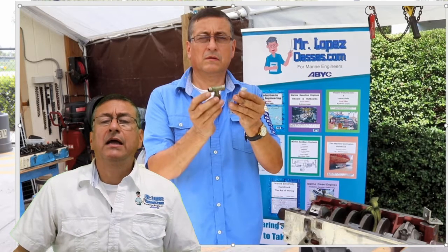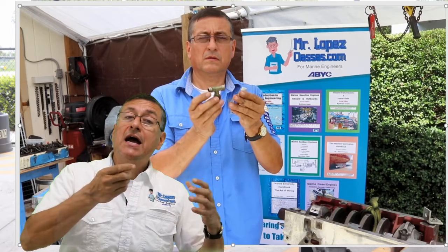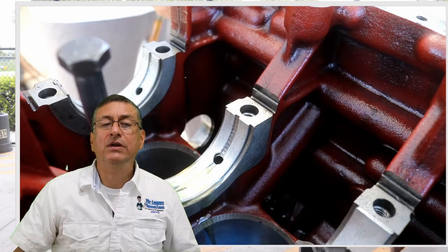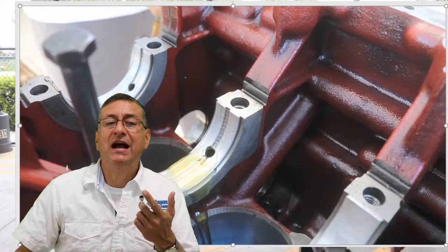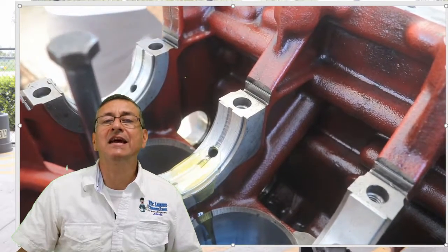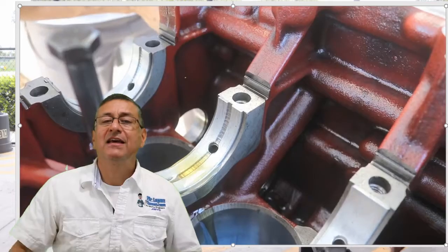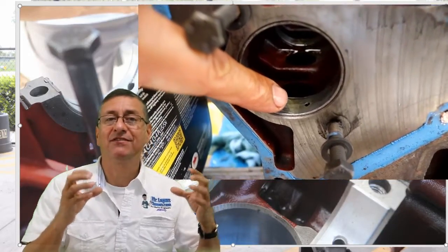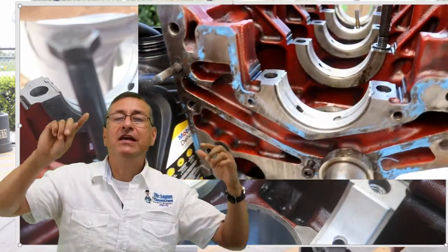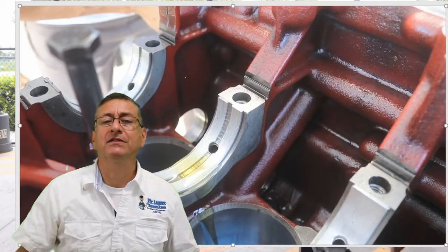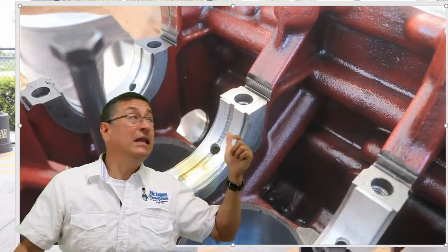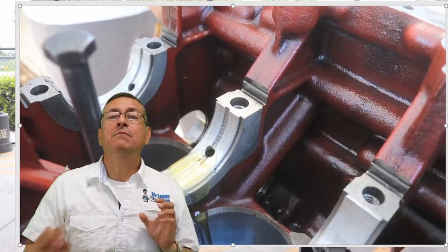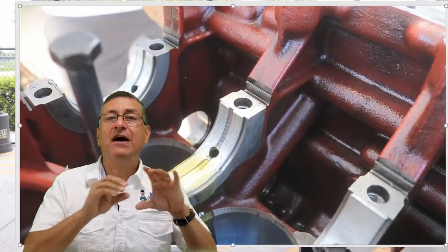Right now the oil passes through the filter, and after that enters the block. When the oil enters to circulate in the block, this is the situation: the oil passes through those cavities and circulates internally. At this moment, exactly the same happens in the plain bearings for the camshaft. The oil enters over there, and you have lubrication in all the plain bearings. Yes, my friends, because the oil penetrates those holes and produces a film of oil between the crankshaft or camshaft and the bearing.